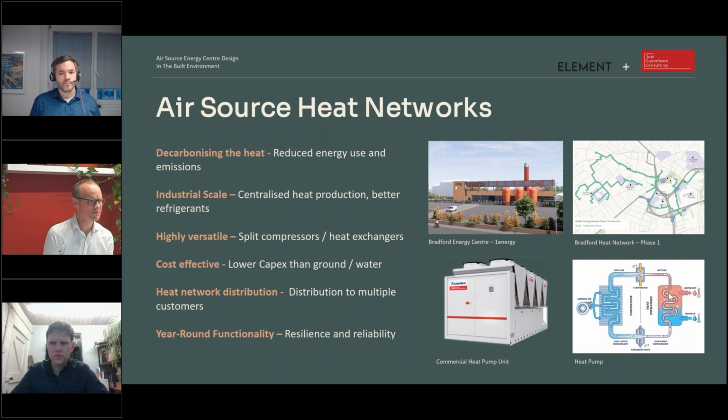The heat pumps at this scale are highly versatile, so we can do things like split the compressors and the heat exchangers. The heat exchanger is the unit that takes heat from the air and effectively makes cold air. I like to refer to air source heat pumps as machines that make cold air and heat up water as a byproduct, and really that is what they do. And the compressors really do all of the work. So with that splitting, there's an opportunity to optimize the design of the air side equipment so that it meets the needs and matches the circumstance.